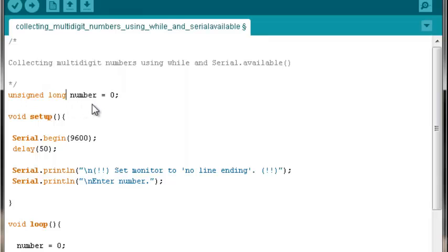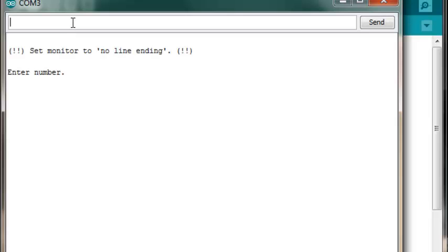That's the big number in the Arduino microcontroller world. So let's upload it and check it with the serial monitor. The number that corresponds to the memory space that's been set aside for the unsigned long should be able to store a number this size, 4,294,967,295. That should be as large a number as we could enter in here. So let's see, does it print successfully? Yes, it does. That's the max, though. If we go one over that, so 4,294,967,296 instead of 295, let's go 96. What's going to happen? Enter.